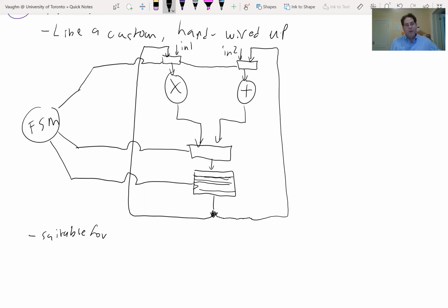Other points people are pointing out, yeah, basically things that make a processor good. If there was also lots of control flow, like if my decisions were dependent, I needed to look at the previous output to decide what to do with the next one, then this architecture also is a reasonable choice. Because it does things serially, it's pretty good at control flow, where spatial hardware can do control flow, but it gets relatively inefficient. You basically compute everything and then use muxes to select which result you're going to take. So a lot of your hardware is computing things that you'll throw away. So yeah, these are all good ideas.